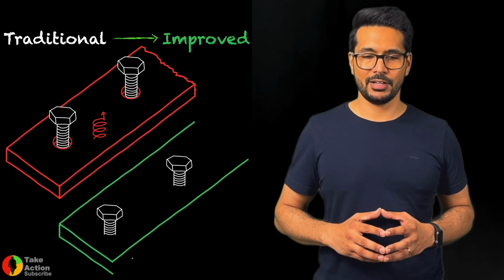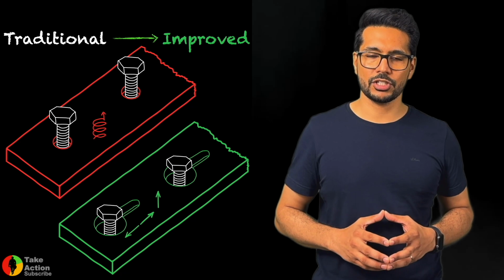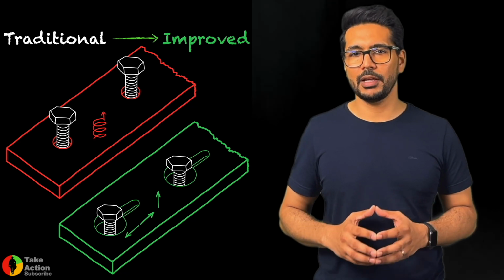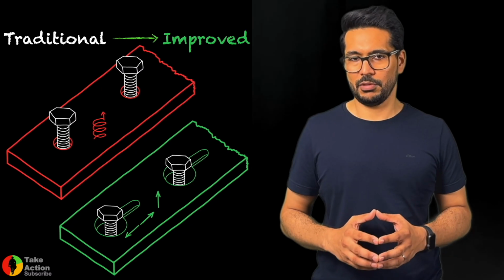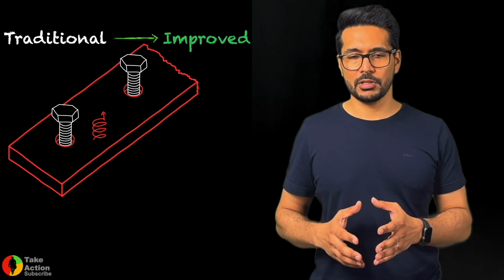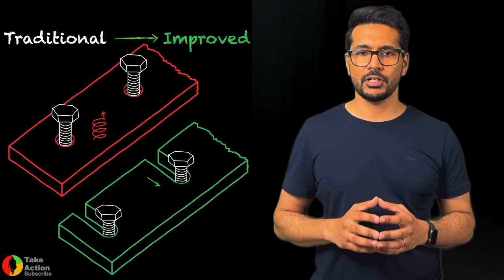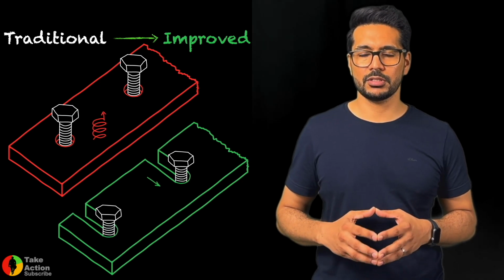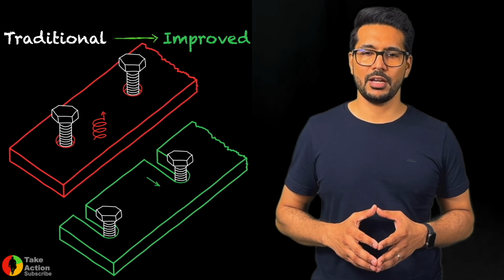After turning one time, the plate will be loose, and then you can slide it in one direction and you can easily remove a plate or any part. So it's one thread loosening system here. Or there is another idea in similar cases: you can have C-slots instead of traditional holes, in which you just unscrew one thread of the screw, and after that you can just slide and remove the part.